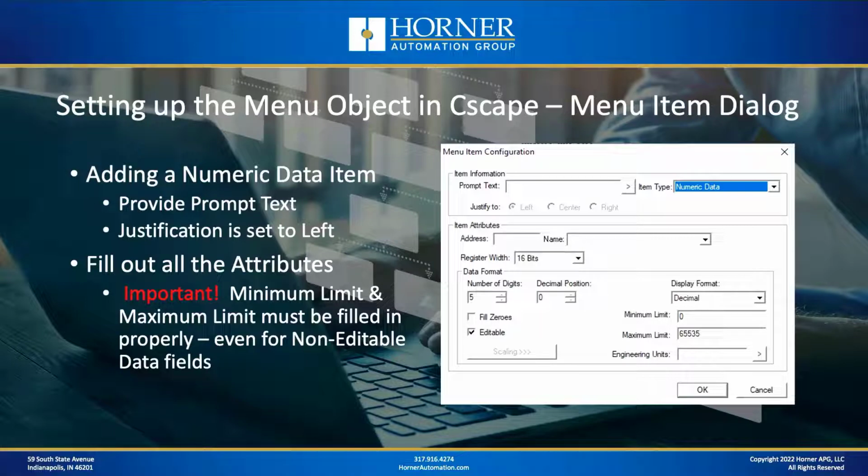And notice again that you have your choice between an editable data field or a non-editable data field. Now, a non-editable data field will be displayed on your menu list, but it won't be selectable. So when a user moves down through the choices, they'll see that on the list, but they won't be able to select it because it's really just there to display data, and read-only data at that. Whereas with a read-write data field, they'll be able to select that and then go in and edit it.